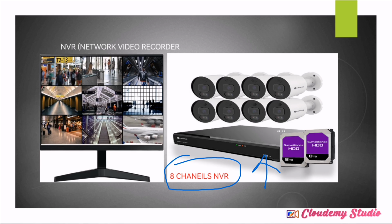When you check on the monitor screen here, there are a lot of cameras. For instance, we have 1, 2, 3, 4, 5, 6, 7, 8. So here, as you can see, there are about 9. It's just an example for illustration purposes. The reason this one has exceeded 8 to 9 is that you can use an NVR that has 16 channels but install only 4, or 8, or 9 cameras.